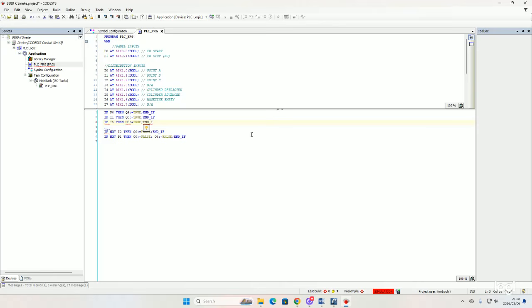So we replace I5, even in our ladder logic diagram, with a memory latch whenever we set a timer for that input. When we inserted a 5 seconds delay for the retraction of our cylinder, we replaced our I5 with M0. So that's what this code means. If I5, then it needs to execute a memory latch, which is M0.